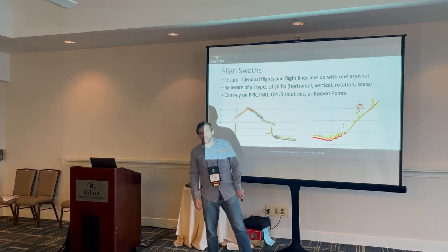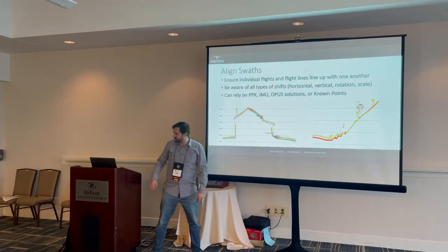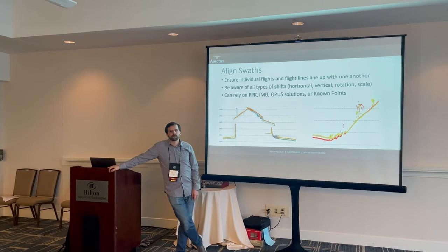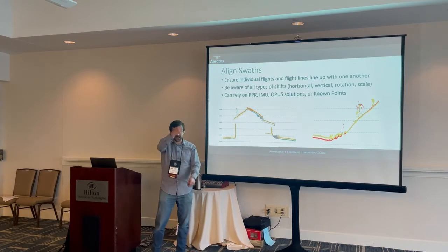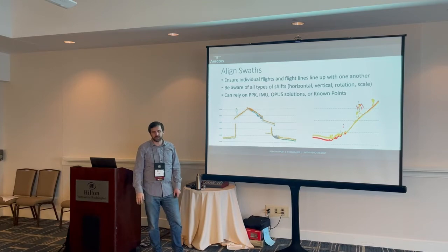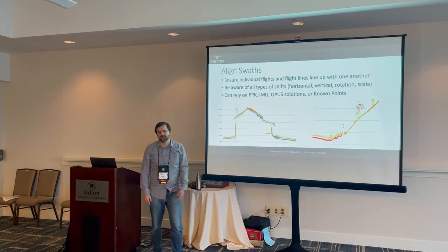That's very, very common. Do existing Phantom 4 Pros have receivers for the RTK data, or is it a specific Phantom 4 that is able to receive those corrections? It is a specific version called the Phantom 4 RTK. You can tell because it has a little cylinder on top that is their dual band. So if you have your standard Phantom 4 Pro, it cannot receive GPS corrections. You need specifically the RTK version.